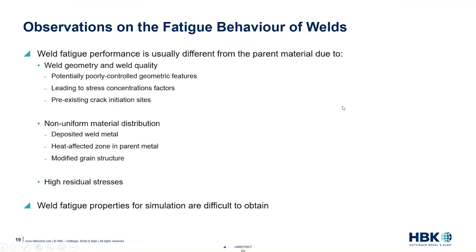And weld fatigue durability is primarily a crack growth behavior because of the presence of pre-existing crack initiation sites, if the weld joints are not fully fused, and also the boundaries between the parent material and weld material.